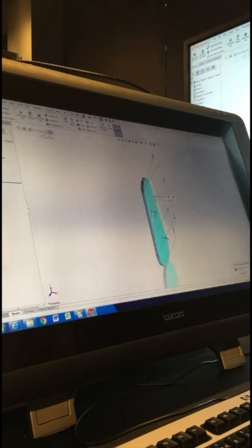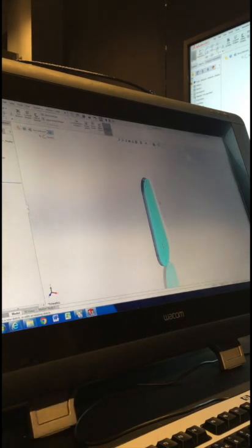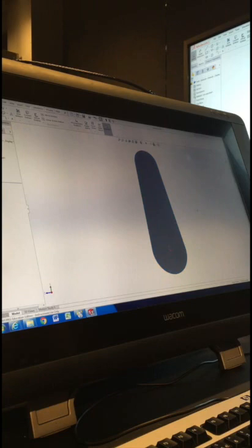So I'm going to select that front face and hit Sketch. And when I do it on a face, it won't automatically make it normal to, so I need to do that manually. So spacebar, normal to. All right, now I can draw my holes.